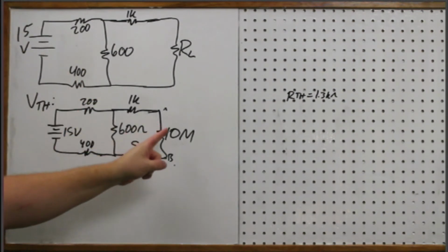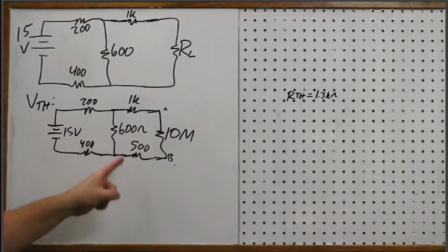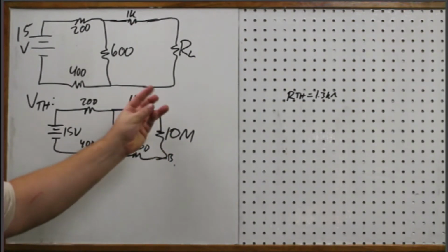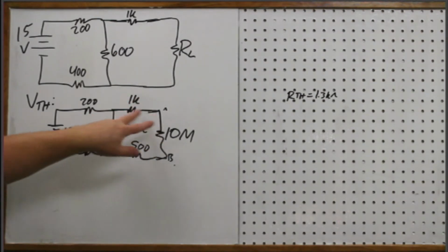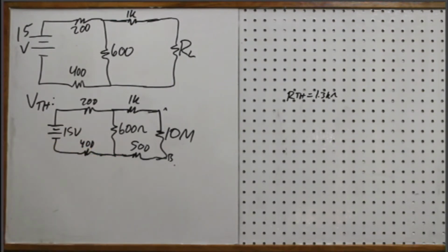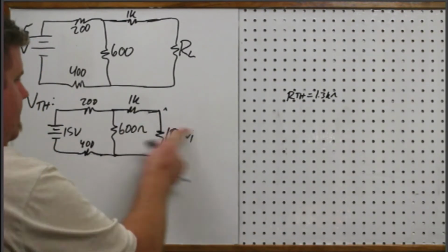You're making the total resistance on this branch over here higher and higher and higher. So it'll have less and less effect the more resistance you pile on. It's still 5 mega ohm instead of 10 mega ohm. So those are hanging resistors. They are not included in the calculation, even though it looks like they should be, right?